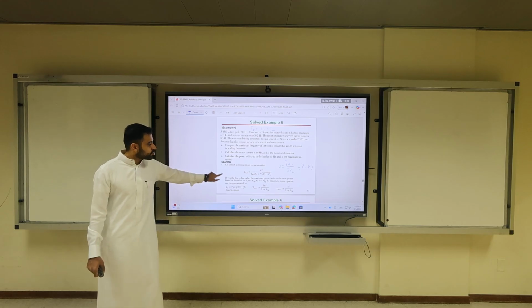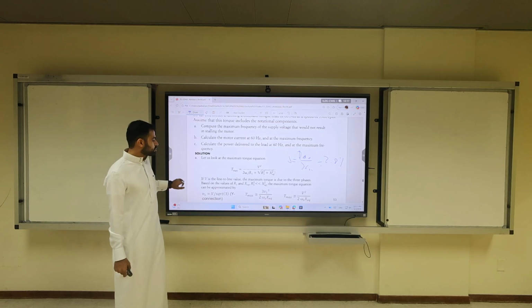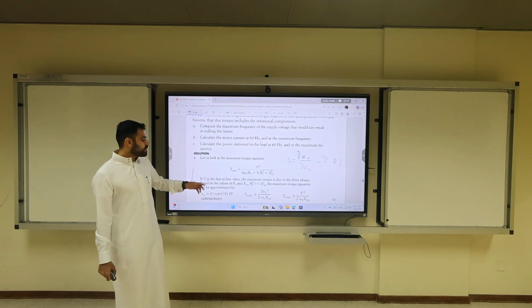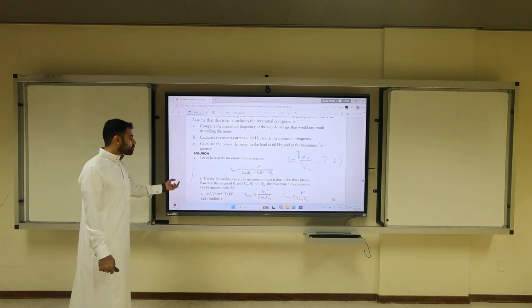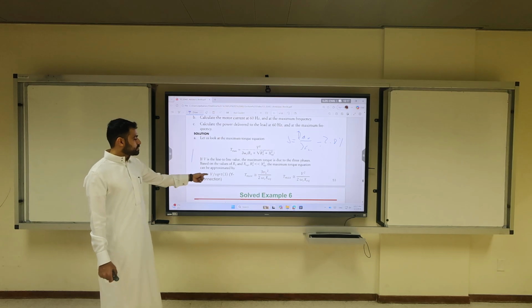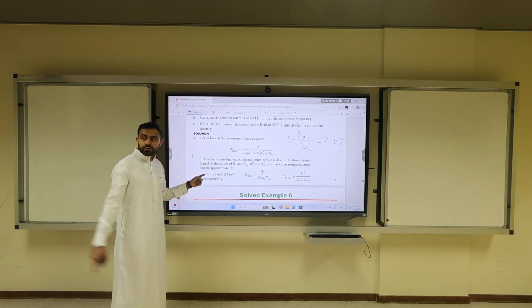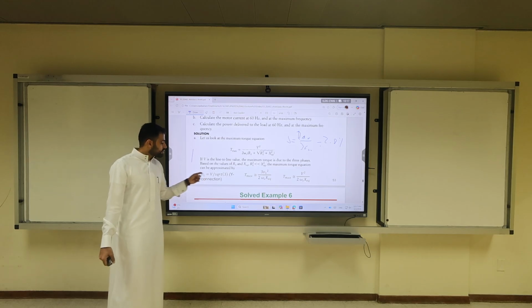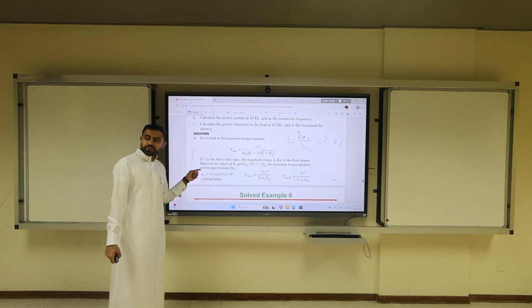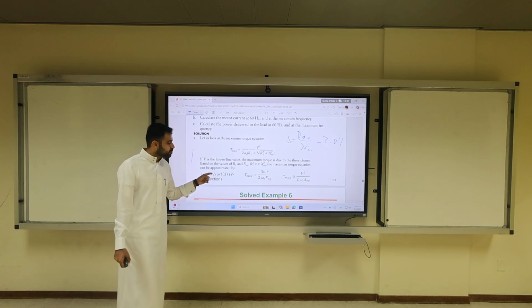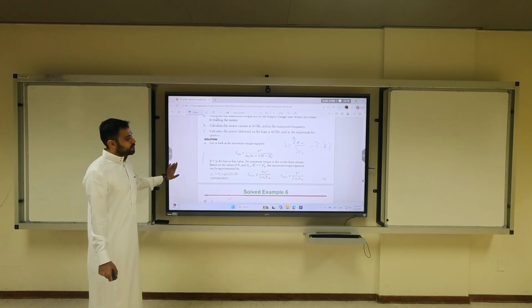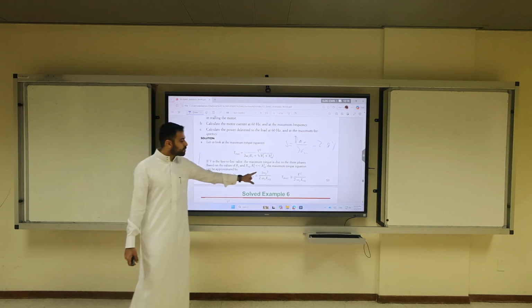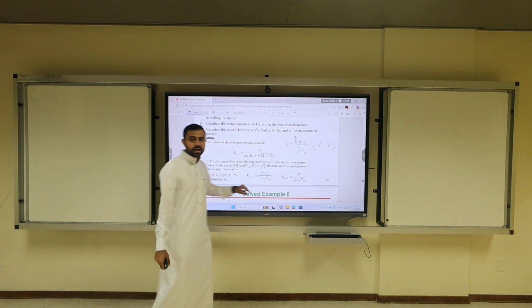So now we have V is line to line. Maximum torque due to 3-phase based on the values of R1 and R equivalent. He is making an assumption here. Assume R1 squared is much smaller than X equivalent squared. So this leaves us with X equivalent here. The maximum torque can be approximated. Remember that V1 is V line over square root of 3. This is V1 in the formula sheet that you developed before. V is line to line. This is phase. It's called V1 or VF. Same names. V alone is line to line. So this is the torque equation if we ignore the R1. This is written in terms of phase. This is written in terms of line to line. Okay?